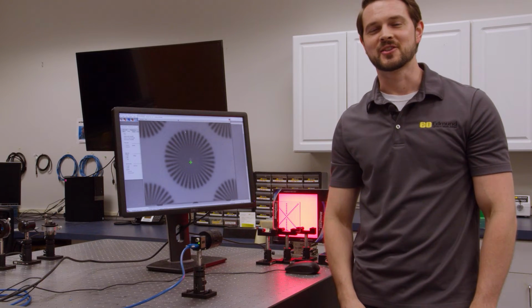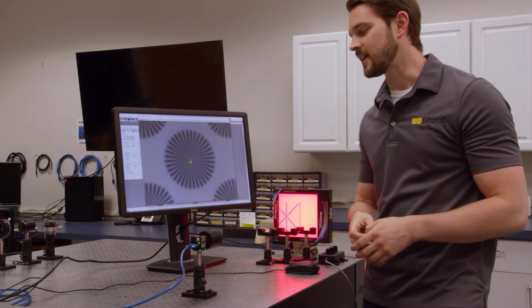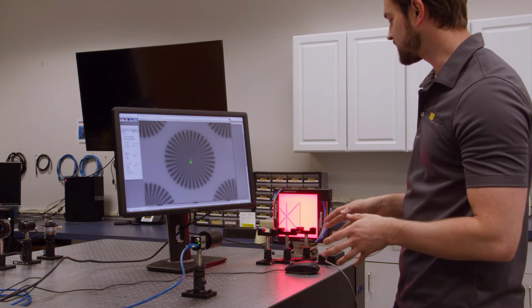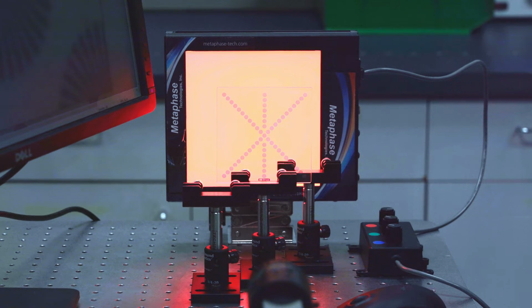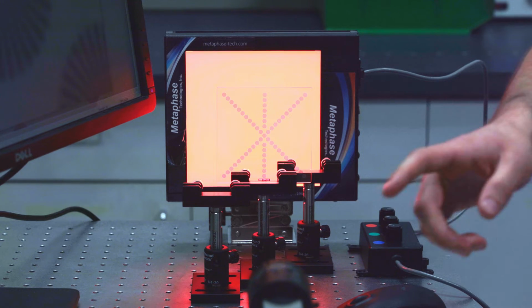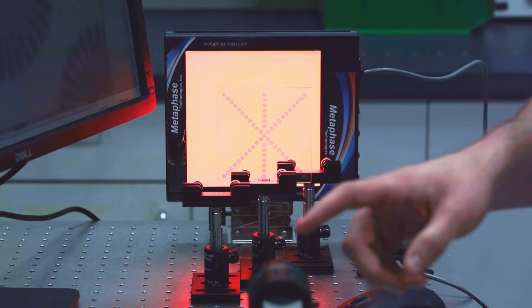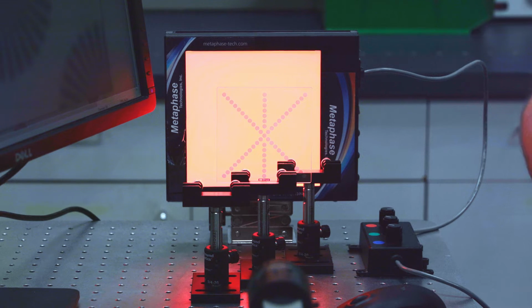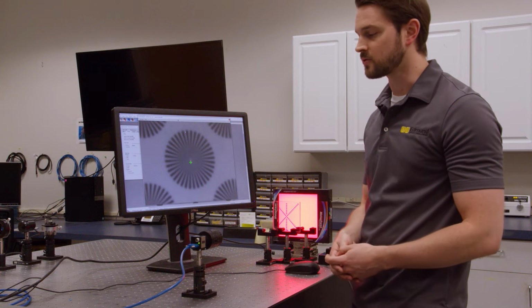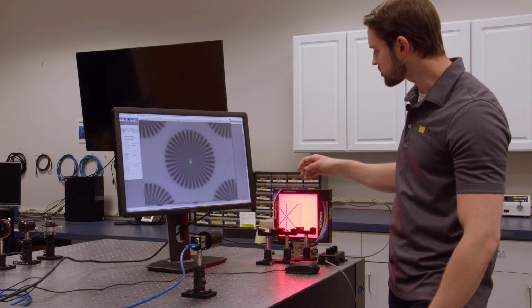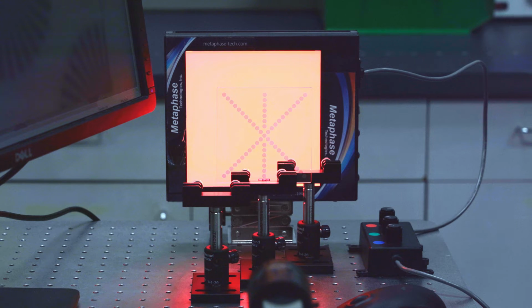Awesome, thank you so much for that information on cameras. Now, while Teledyne was talking, I actually went ahead and switched around some stuff on our setup here. I removed our two other USAF targets, and I just left the star target here. I changed out our camera to an IDS camera, one of their CP cameras. This has an IMX264 in it from Sony. This has the 2/3 inch sensor and the 3.45 micron pixels. And then I also changed our light to a Metaphase Technologies RGB backlight. So this backlight is going to allow us to change colors, go from red to green to blue, because that's what we're going to be looking at in this portion of the lab.